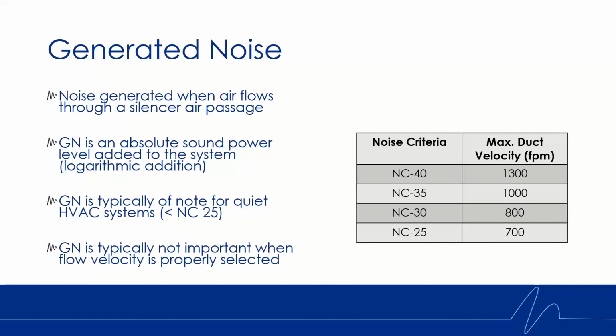There are times when we do want to consider the generated noise, and that would be for when we have very quiet systems. So let's say NC20 or lower, this is going to be a performance space, a recording studio, something of that nature.